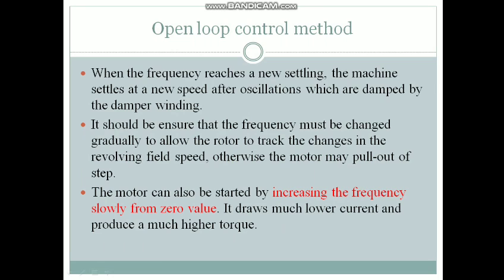It should be ensured that the frequency is changed gradually so that we can control it. Otherwise, if the frequency changes drastically, increasing by a large amount, the motor may not be in our control and may pull out of step.